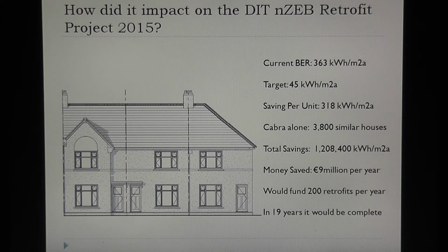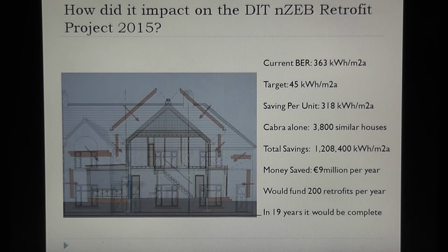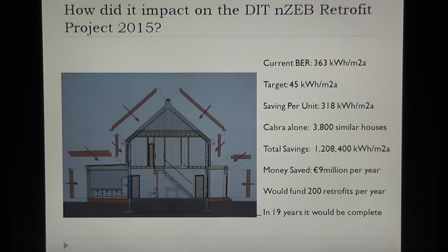One of the solutions to the project is to prefabricate the insulation elements, to put some extensions on which significantly help to reduce the losses through the floor to the soil block. And in fact, it's possible, by combination of external insulation and prefabricated extensions front and rear, to retain the existing ground floor in place and achieve the NZEB target for a retrofit.